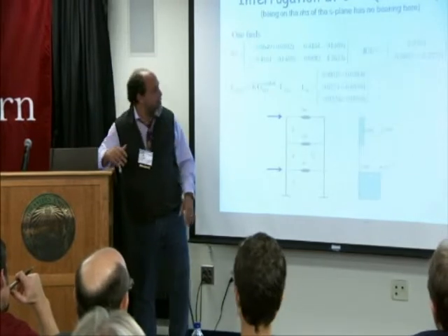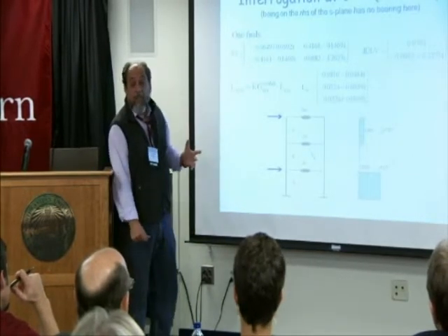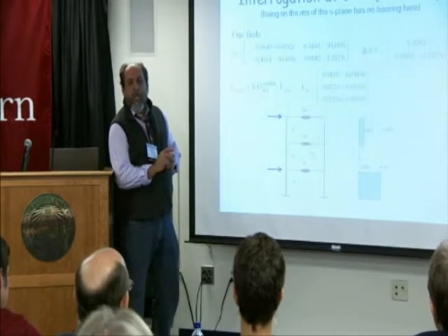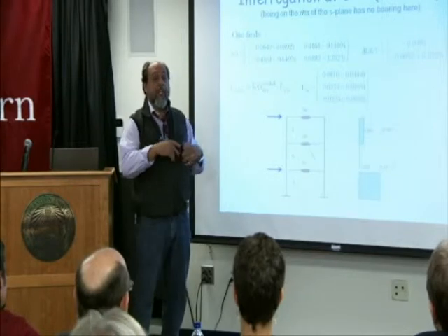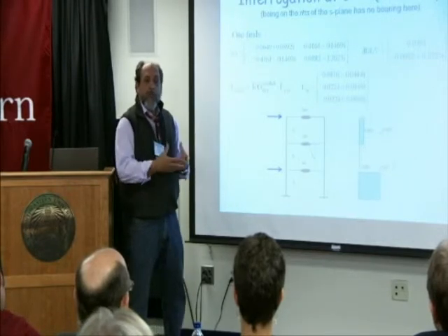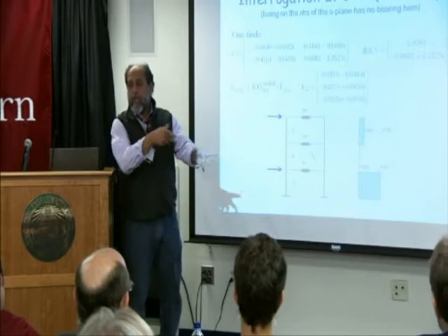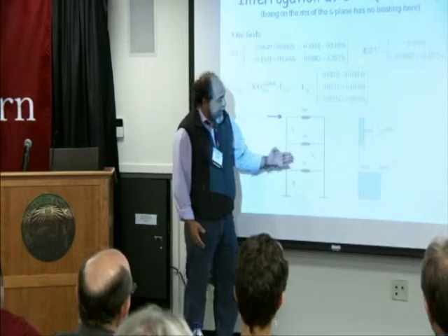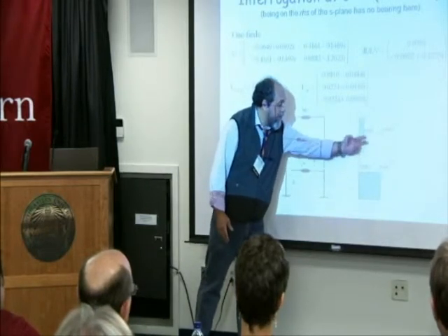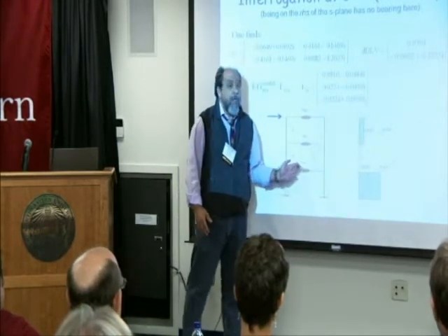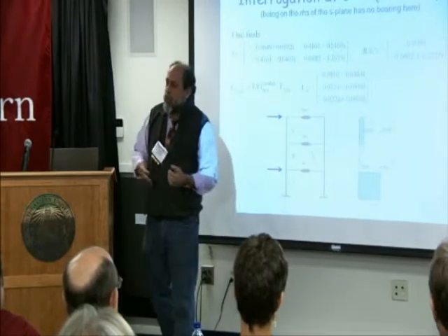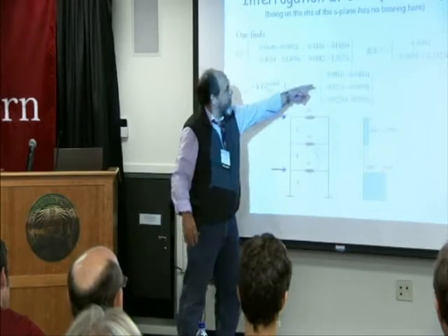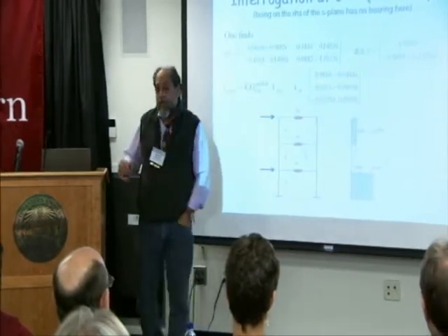And the one interesting thing that most structural engineers at least find amusing is that what happens in the dynamic case is you can take the problem to be the calculation of a stress field that is complex. So you actually load the structure with 3 plus 4i loads and 5 plus 9i and so on, and get a complex stress field that in this case, as you can see, here is shown with magnitude and phase, bypasses the damage. There is really nothing to it once you think about it a little bit, but it's kind of amusing to find loads with imaginary parts.